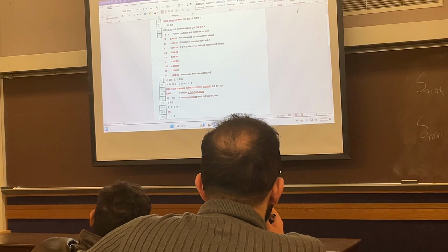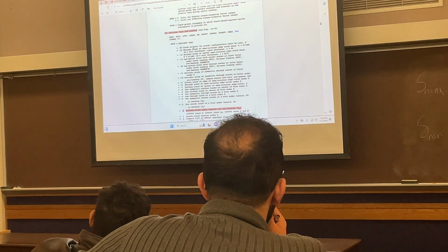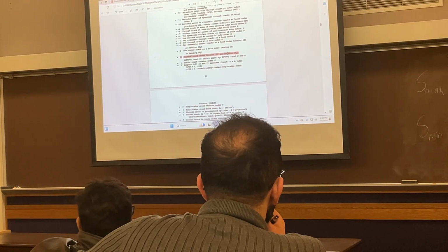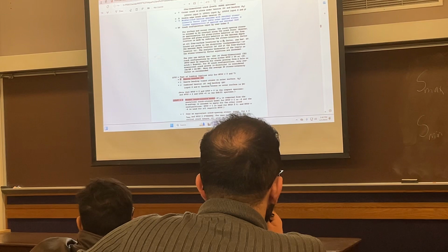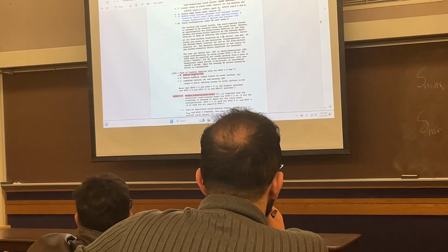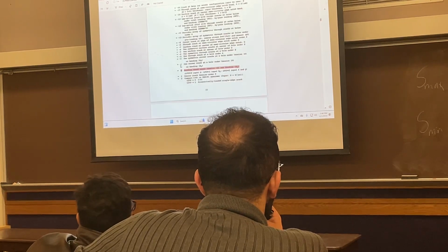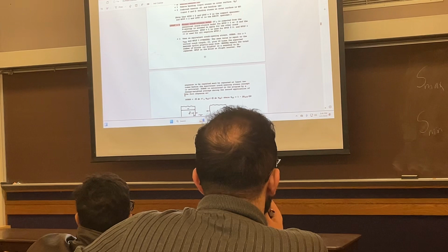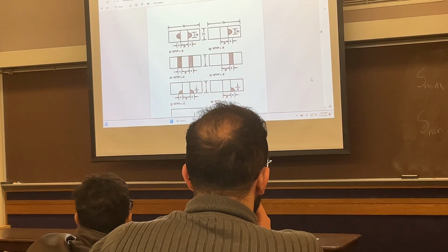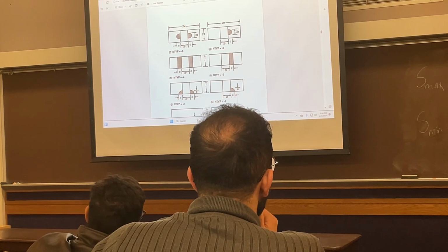So it's 0 and 0. If you look at that manual, 0 is the surface crack under tension and bending. When L type is equal to 0, it's just tension. So for surface crack under tension, N type is 0 and L type is 0. So you need to read this description and look at these drawings to see which one is your specimen and crack.